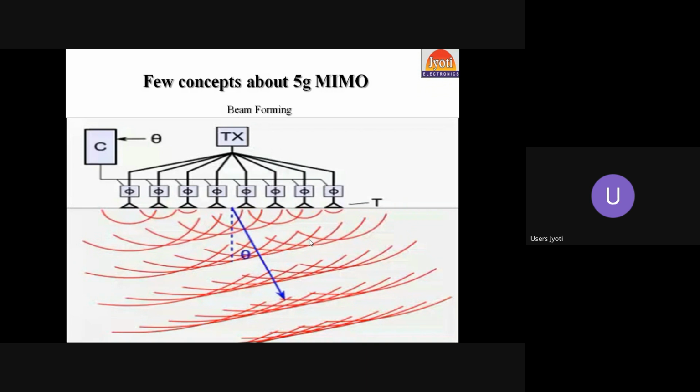I use all the antennas and give different inputs, and it will give the output in a particular theta direction. Basically, if I don't give any amplitude and phase difference, the propagation will be in the theta equal to zero direction. But if I want some tilt on the right-hand side, because my inputs are different, it will give a particular direction, and I receive some radiation pattern.